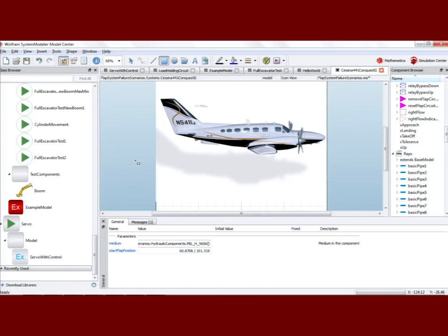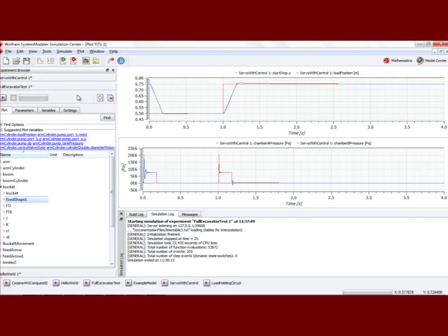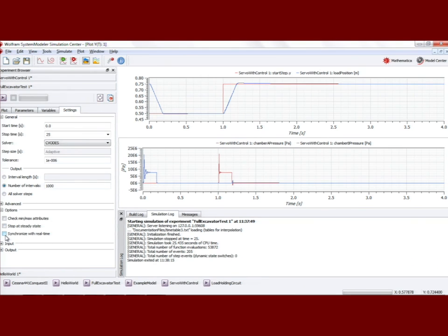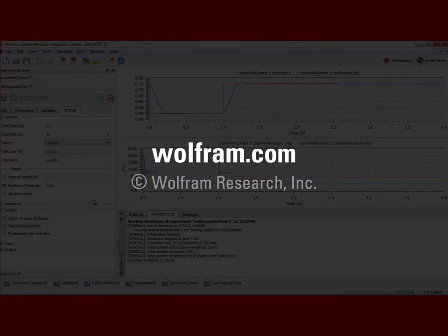One thing I don't quite understand, if I see this, I can simulate, but if I wanted to do a real-time system and have the same modeling being done, is there a way to act on events in real time? Yeah. So you can connect, basically, now when I simulate, I didn't simulate in real time, but you can set systems to synchronize with real time if you like to, and you have several ways to talk to the simulation while doing that. So one of my standard examples I haven't brought with me is a quadricopter where we have the model and then we have a gamepad to control it. So you can connect kind of anything and run the simulation that way. And then the other thing is, once you have it, you want to deploy it into a real-time system, a hardware-in-the-loop system, then you can use the new functional mockup interface, the unit there, to deploy it into the hardware-in-the-loop system.